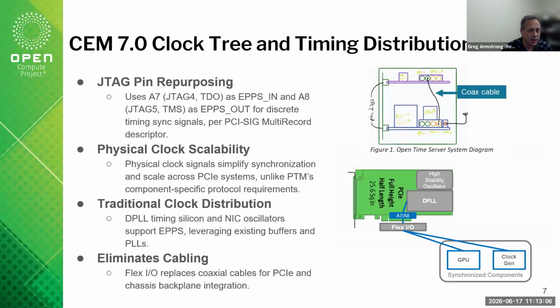You can start synchronizing physical layer clocks with the 10 megahertz, or even have a redundant or alternative means of seeing where that 1 hertz marker is, because that timing is coming in from a time card itself that you want to distribute within your system.